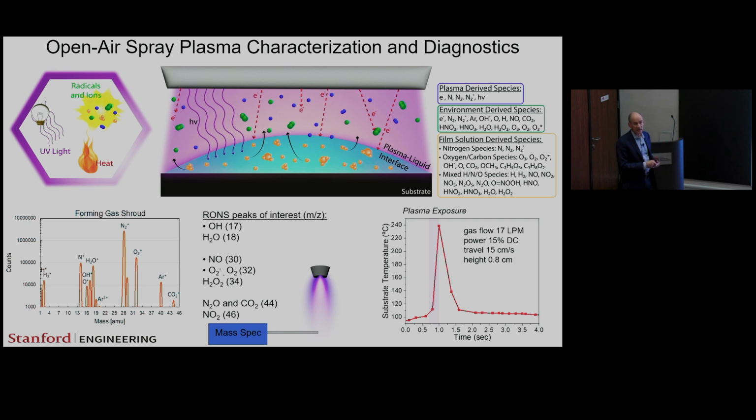And then, of course, there's heat. Now, we don't want too much heat, but typically, if you ramp up very quickly to around, as shown over here, to around 240 degrees Celsius, and then cool down, this is the process window in which we would operate.